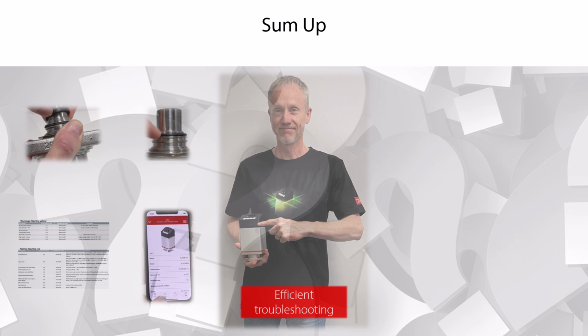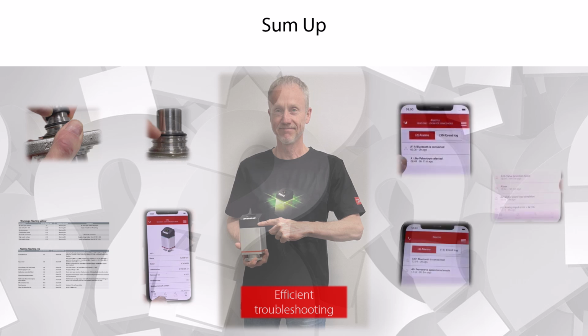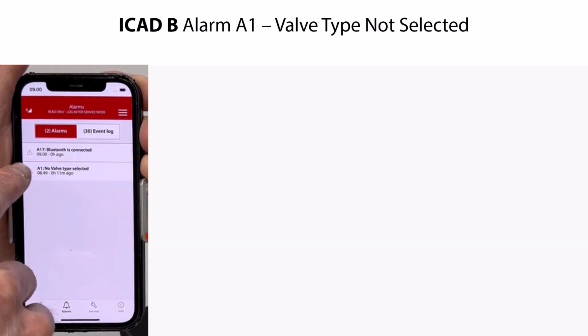All this ensures you an efficient ICAD B troubleshooting procedure with the intuitive warning and alarm structure. So let us now look at the most common ICAD B alarms A1, A3, and A9, and how to solve the issues causing these alarms. The ICAD B alarm A1 is triggered if you have not configured a suitable valve type in the ICAD B.